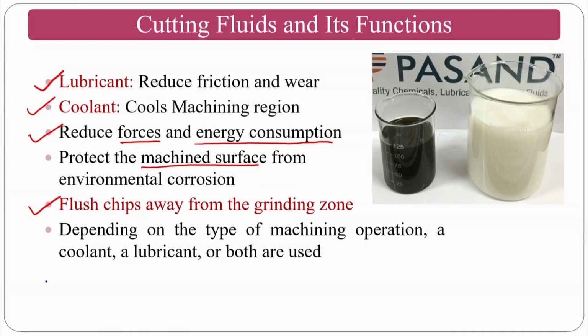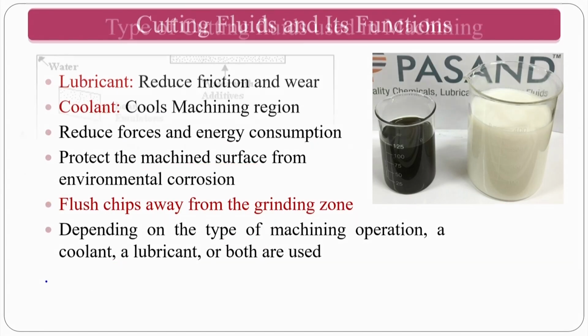So, depending on the type of machining operation, a coolant, lubricant or both can be used. Normally, in this condition, you have an abrasion effect and a temperature effect. That is why you need both lubricating as well as cooling properties. You can see here, this is the pure one that is purchased. Whenever you mix it with water, normally it will come as a milky white color of the cutting fluid.